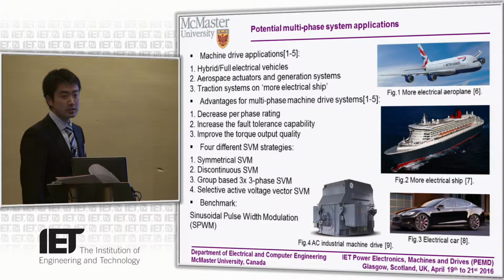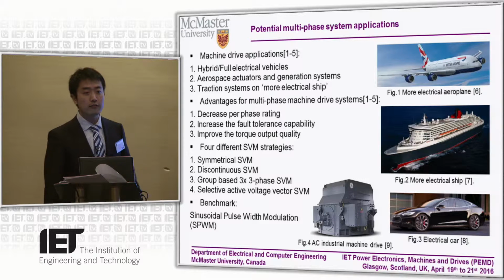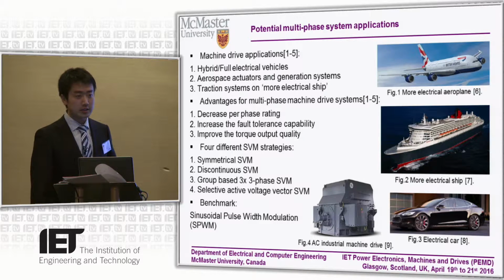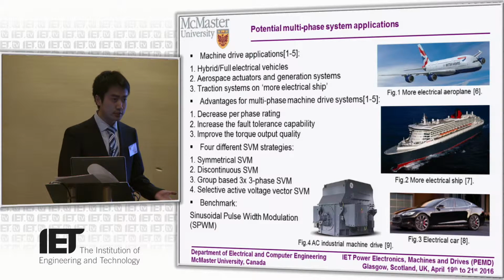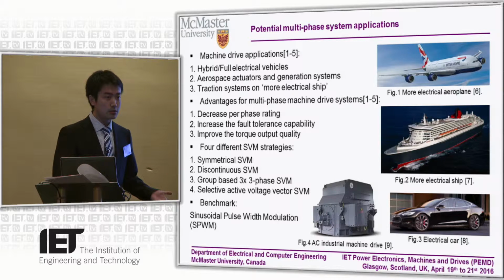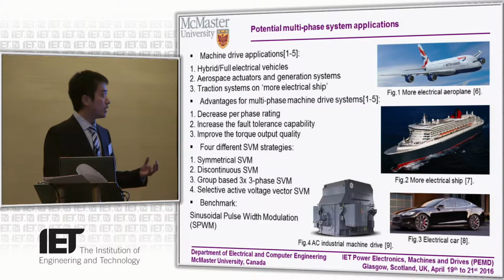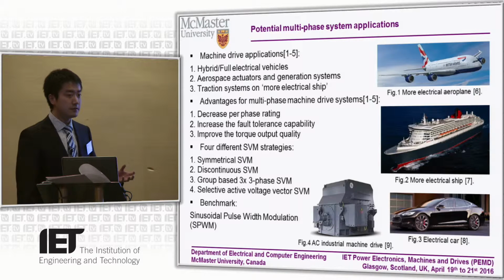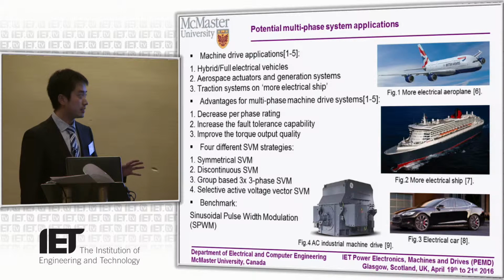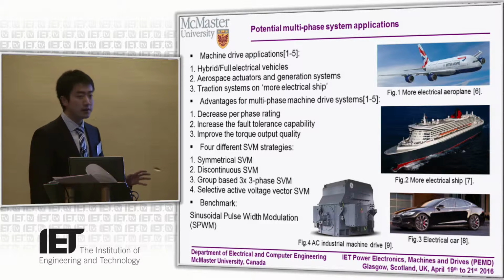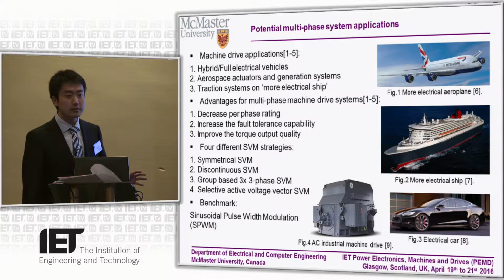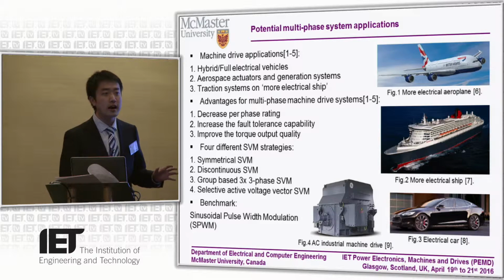Due to the application of power converters, and also no direct online operation, it's not necessary to use three-phase systems. So we can use the onboard power electronics to achieve multi-phase systems like five-phase, six-phase, seven-phase, nine-phase, or even higher phase numbers.